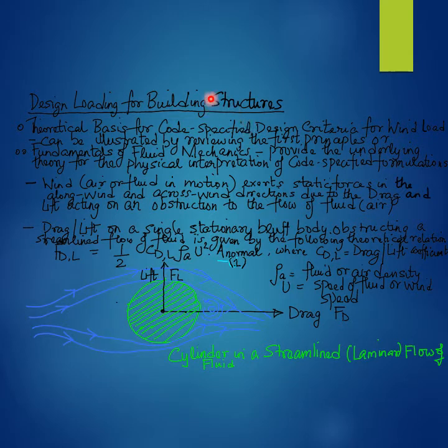Recall that in the previous slide we had mathematically derived the theoretical basis for the code specified design horizontal seismic base shear, that is the design horizontal or lateral earthquake force, starting from the first principles of the theory of structural dynamics or the fundamentals of dynamics of structures.